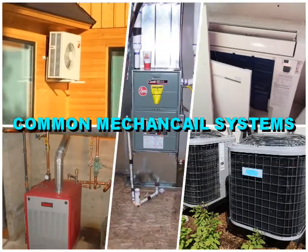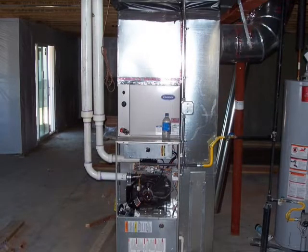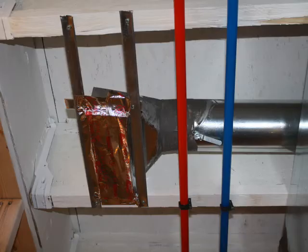Common mechanical systems. Okay, so let's talk about the types of mechanical systems commonly used in a residential project. Most places in the United States, we have a forced air type system. It's commonly used. What's a forced air system? A forced air system will use a source of heat or cool, so we've got a heat exchanger or a coil. The conditioned air is then dispersed throughout the house by designed ductwork through vents or registers.